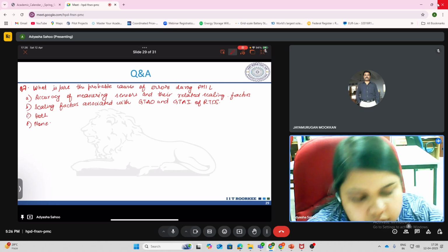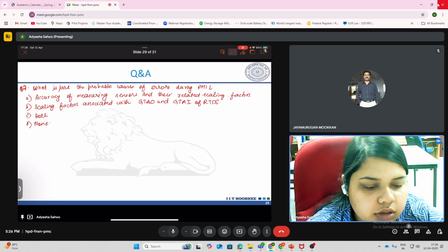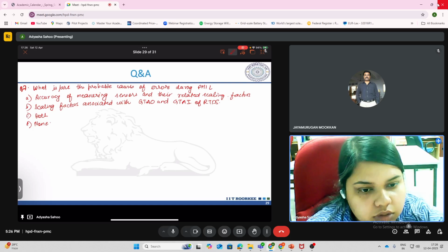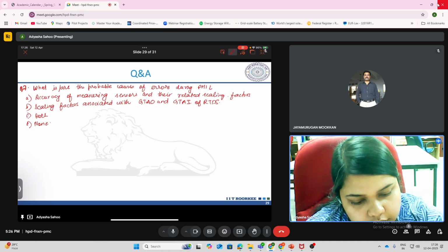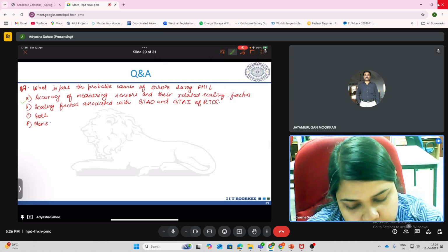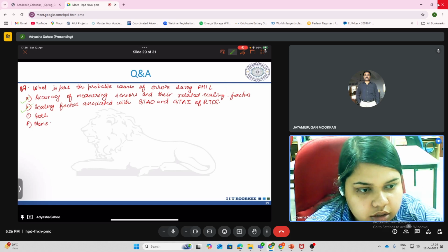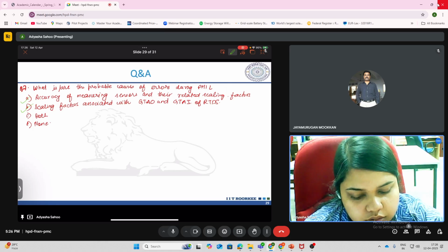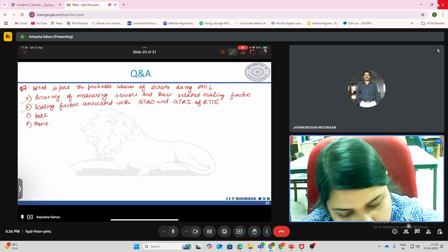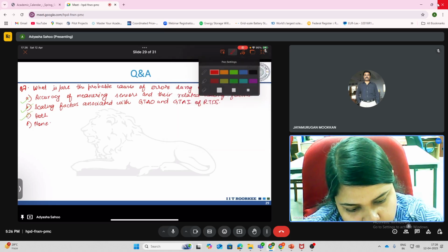So obviously we monitor the device under test using the sensors, the voltage and current. Basically, we were sensing and giving it back to the RTDS through the GTAI card. So that will affect the operation in the PHIL. Scaling factors also will, basically when we were going from RTDS to the GTAI card and similarly back to the RTDS through the GTAO card, we had a scaling factor at both locations. So that accuracy will also affect the PHIL setup experimentation. So both is the correct answer.